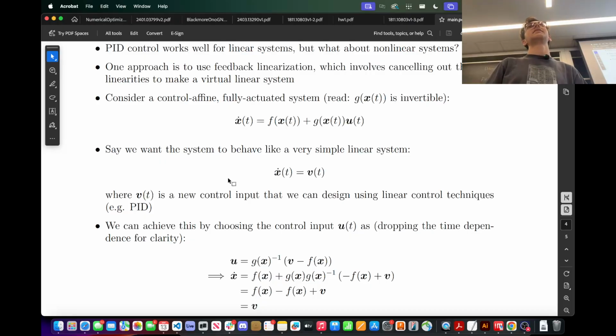So you can apply feedback linearization on just the attitude part, when controlling the orientation of the vehicle, because you have full control authority over the orientation. You can do partial feedback linearization on the attitude part, and then do something else in an outer control loop for the position. Those kinds of schemes are very universally used in drones and rocketry, a lot of aerospace applications. So this stuff is bread and butter of control theory.